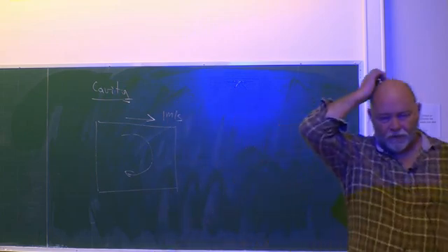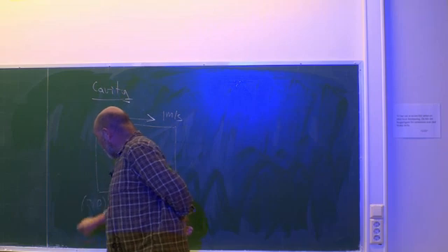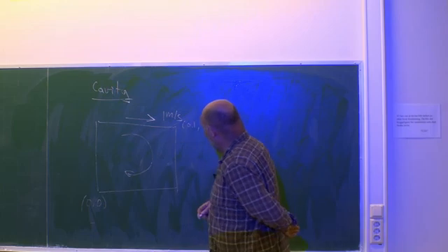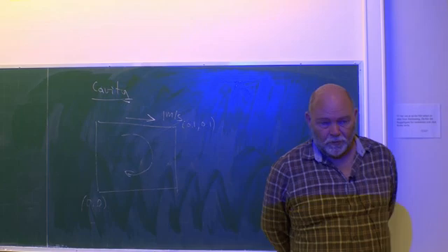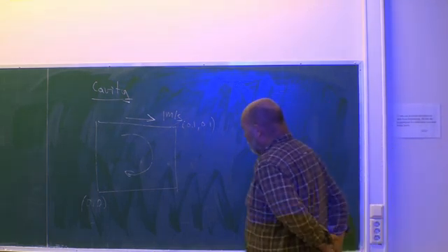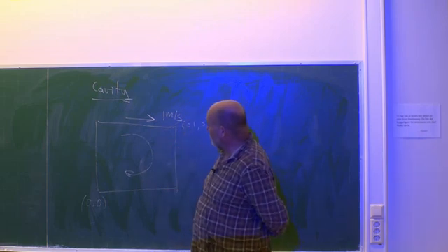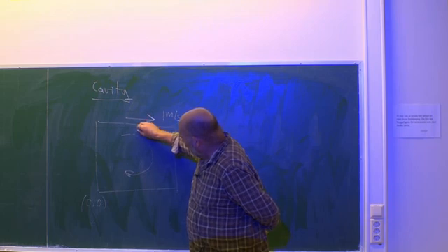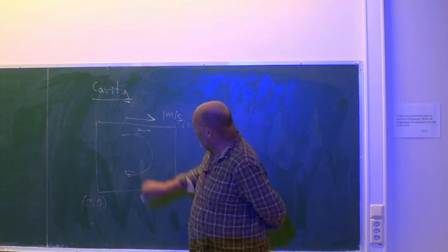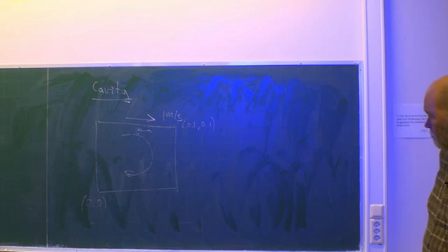The classical cavity setup was at location 0, 0 down here, and then 0.1, 0.1, a two-dimensional problem. During startup of this cavity, laminar, nice, easy, but transient, I want a velocity up here, just below the moving wall. I want to trace that one as a function of time.